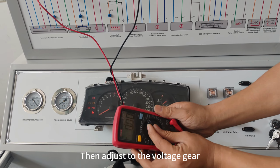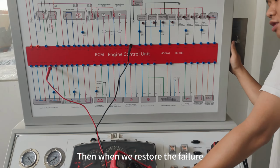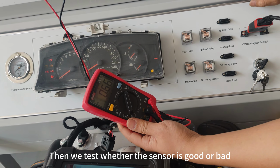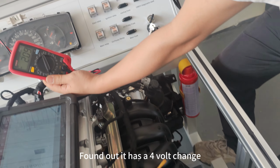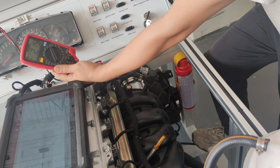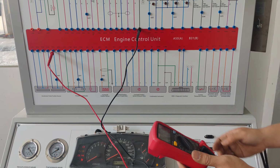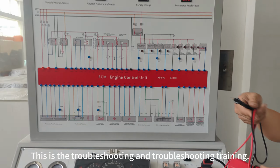Then adjust to the voltage gear. It turns out there's no voltage. Then when we restore the failure, it has voltage. Then we test whether the sensor is good or bad. We can press the pedal. Found out it has a 4-volt change. This is the troubleshooting training.